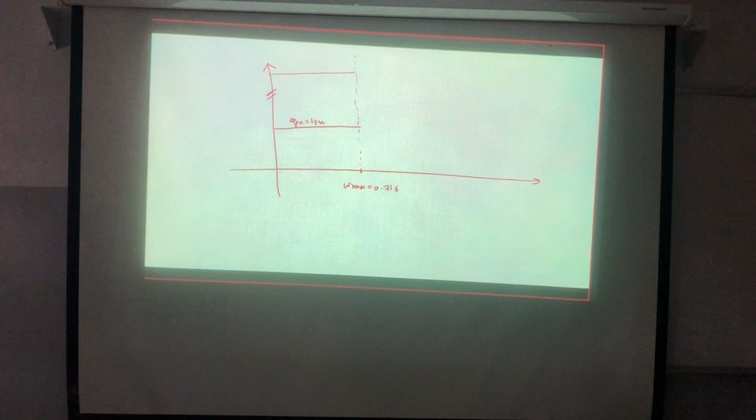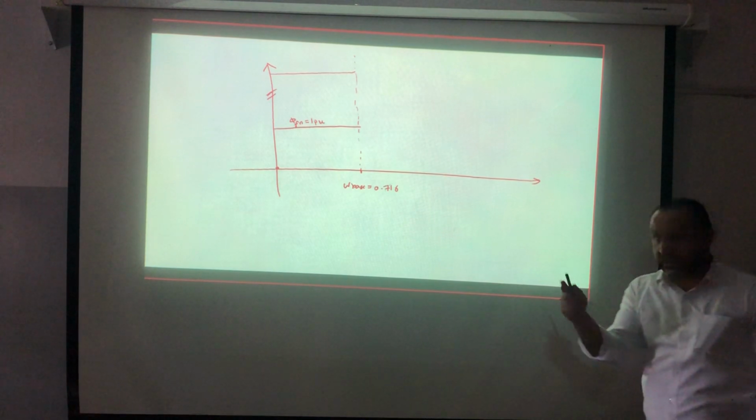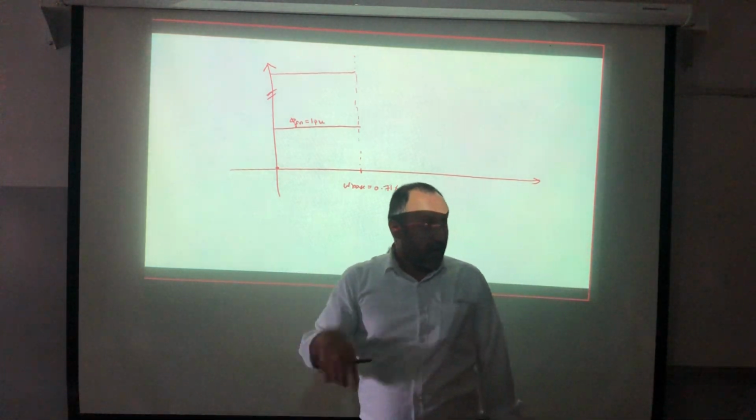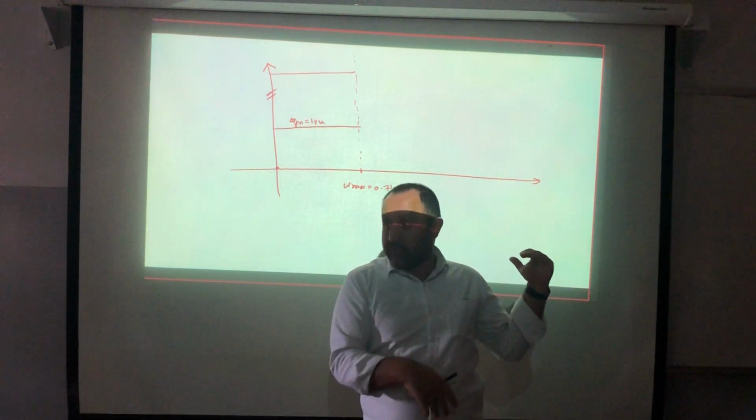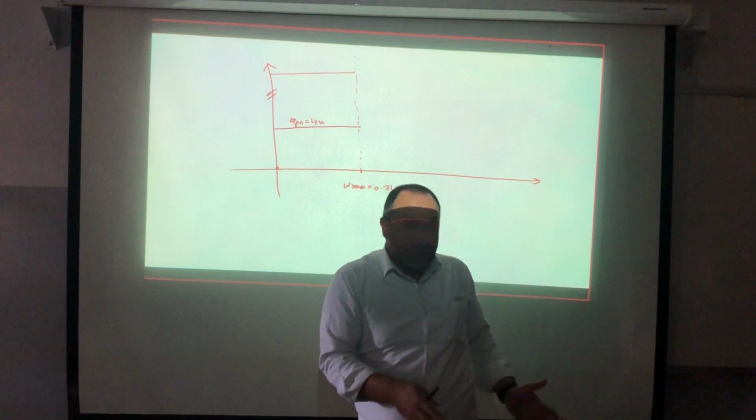Good. What about the back EMF? It will start from 0 until 0.716. The back EMF, EA, is equal to K phi omega, and in the armature voltage control, phi is constant.